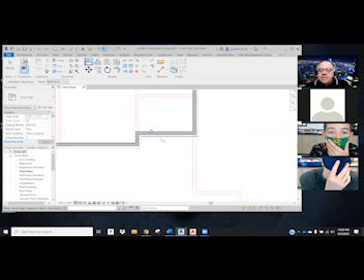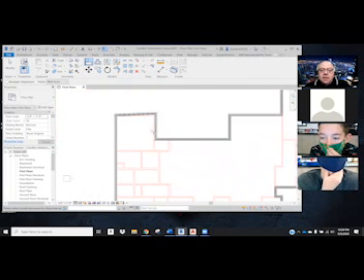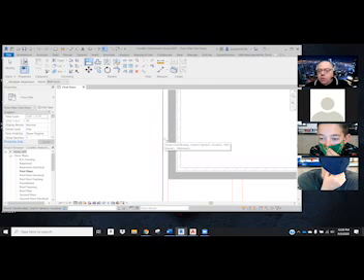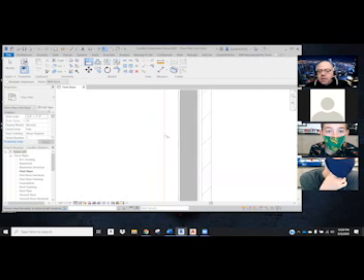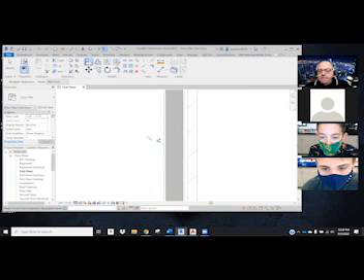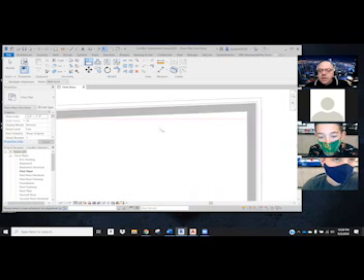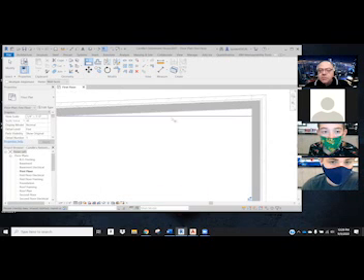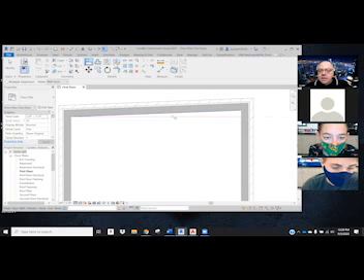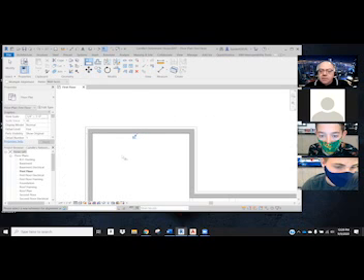Okay, now that same tool is going to fix my other errors, of which there's a few. Up here, I missed the boat like a whole wall thickness, and I need to be on this point. So again, I pick the red line of my AutoCAD file and the edge of the gypsum board, the wall face, and it lines it up. Well, that's easy. The lines are all straight. This one's crooked. Well, the nice thing is it will fix that as well. The AutoCAD line and then the edge of my gypsum board, and it will straighten that all up. So I have that all into place.